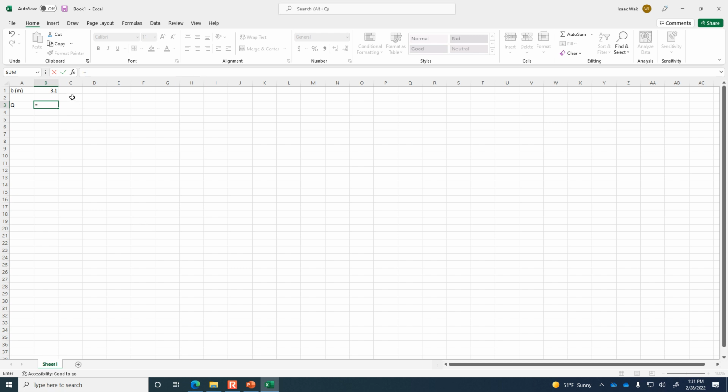So it's going to be this guess of B to the power of 5/3 times the slope to the 1/2 power, so 0.01 to the power of 0.5, divided by 0.011, because that's my n value, and then times, I'll put this in parentheses here, 2 plus B to the power of 2/3, so 0.66667.